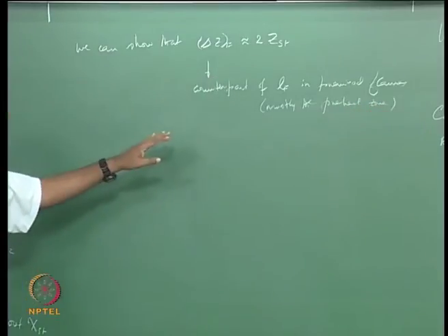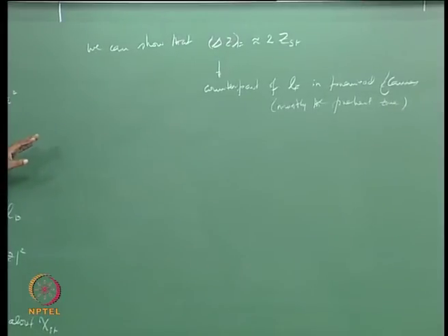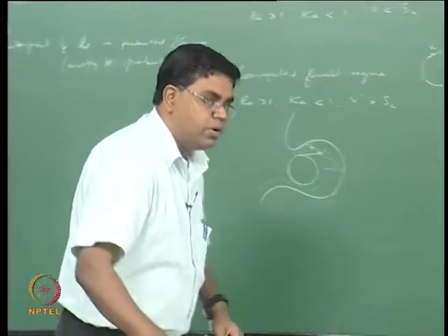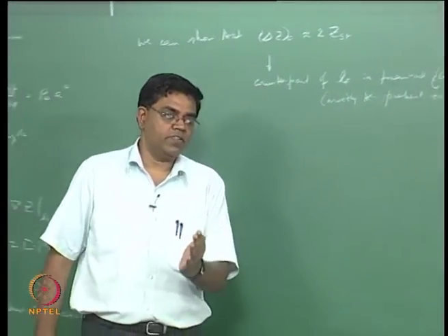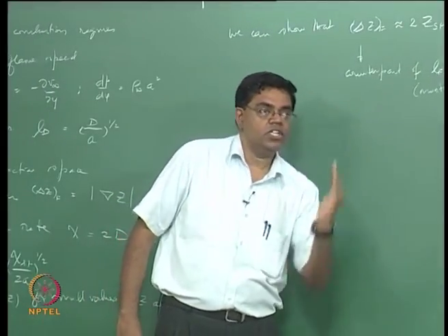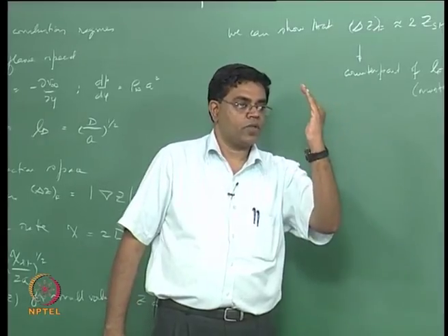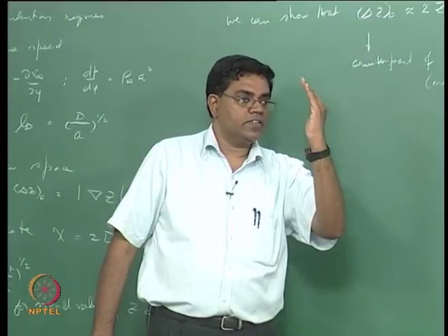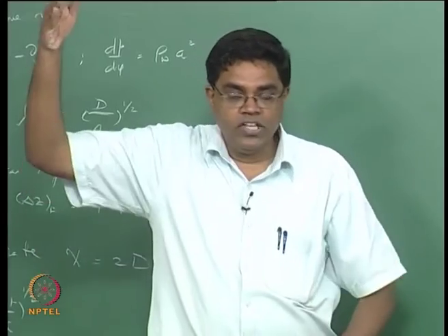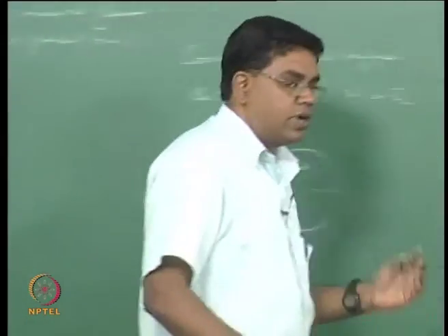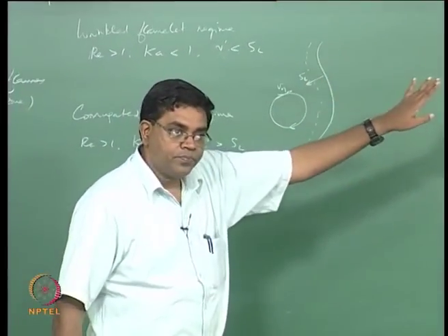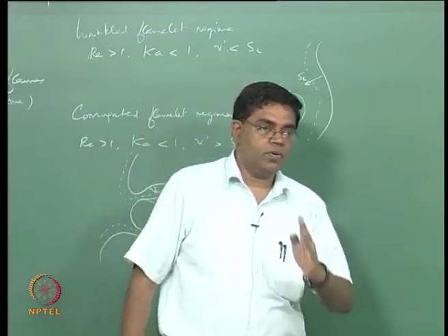And we did point this out when we were doing diffusion flames, if you recall. So when we did the laminar diffusion flames, what we pointed out was the Burke-Schumann assumption was essentially saying that the flame is a sheet along the stoichiometric surface, but that was essentially the reaction sheet. So it's sort of like saying in the premix flame, if you now think about only the reaction zone as a sheet, but consider the thickness of the preheat zone, like the way we have been drawing pictures here. Then what happens in the Burke-Schumann problem?